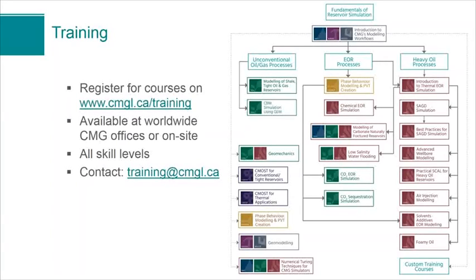For biodegradation, you would have to add components for something in the reservoir that is causing this biodegradation, and set up a reaction with that component. You would of course need some kind of laboratory data to tune that reaction.